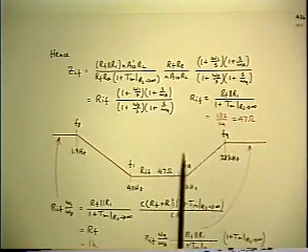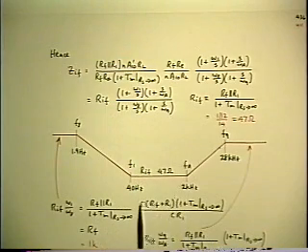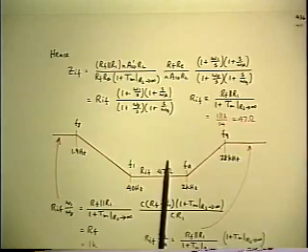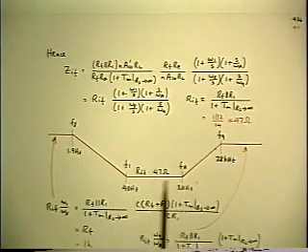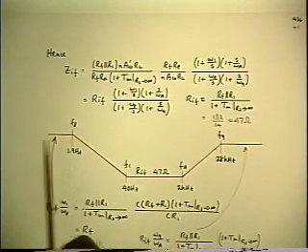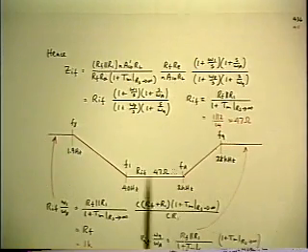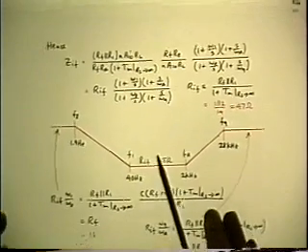So I won't bother with the details, but this is the result. It's a mid-band value, which is low, as expected, because it's shunt feedback. And it rises outside the range where the loop gain starts to go away, and it does level off at both ends. So it's got 2 poles and 2 zeros, and it's a more complicated result than the output impedance was.